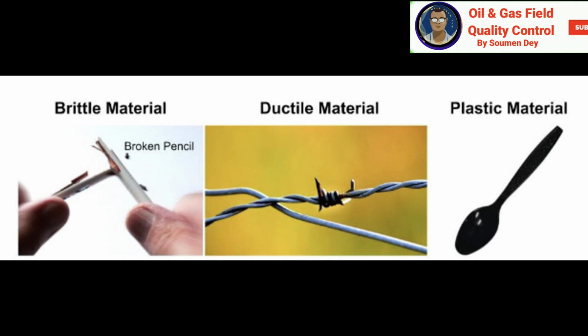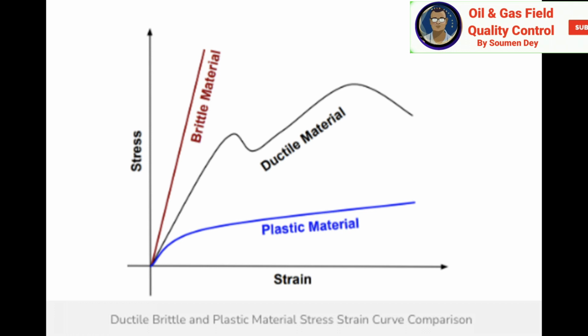Ductile material has different points of ultimate stress and fracture on the stress strain diagram because it has elastic and plastic deformation. Copper, aluminum and steel are examples of ductile material. For example, steel sheets regain their initial position up to the elastic limit during the sheet metal bending process. But after the elastic limit, the material starts showing plastic behavior and does not come back to its original position. If we continue applying force beyond the elastic limit, the material will break at the fracture point.